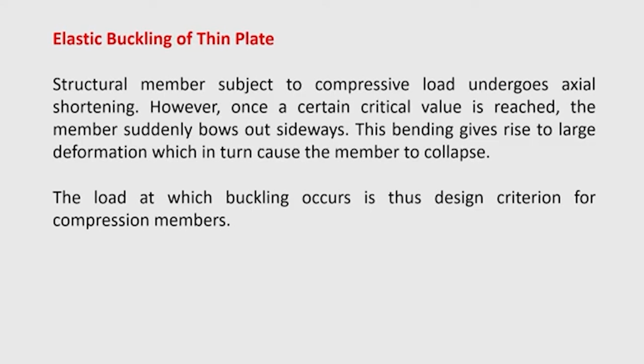This bending gives rise to large deflection, which in turn causes the member to collapse. So, buckling is a condition when instability arises. That is a bifurcation problem. The load at which buckling occurs is thus the design criterion for many compression members.